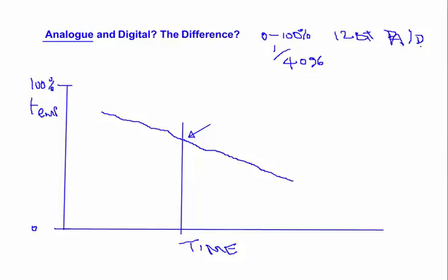So if I was to amplify a small section of this, and I'm going to exaggerate this for the effect, then as you might expect, what you find is that your signal comes down in steps. And the size of those steps represents 1/4096th of the range of the instrument.